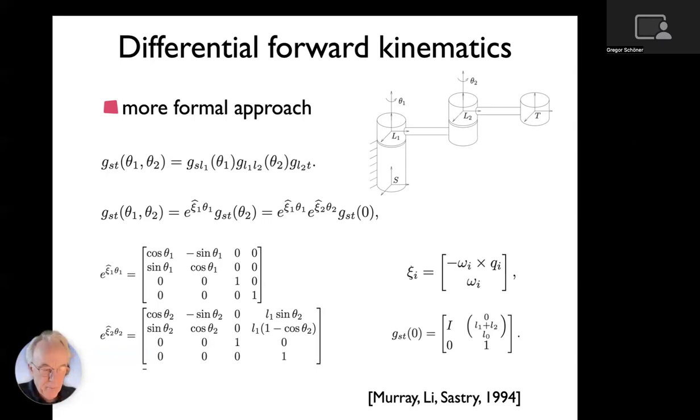And in the two directions, you will know where an object is in the base frame, and you want to have a desired set of how an object should be in the tool frame, for instance, for you to grasp it. And you need to find the configuration that will achieve that, given where the object is relative to your base frame, because you have some camera, you have some coordinates from a plan of the environment. And so this connection between these two frames can be written as a chain of coordinate transforms. So you transform the different frames into each other.